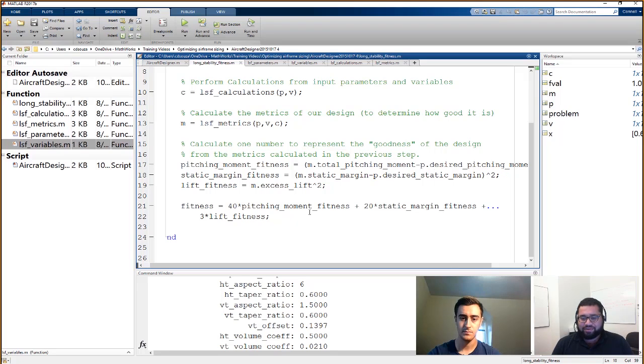These values could potentially be put into a simulator, and you can figure out if your aircraft is performing like you want it to perform. Going back to the variables, I think the wing area is a lot more important than the tail angle of attack in some ways. Given the range we had on our wing area, changing your tail angle of attack by 1 or 2 degrees isn't going to destroy the aircraft, but changing your wing area by like 10% could have some pretty detrimental effects on how it flies.